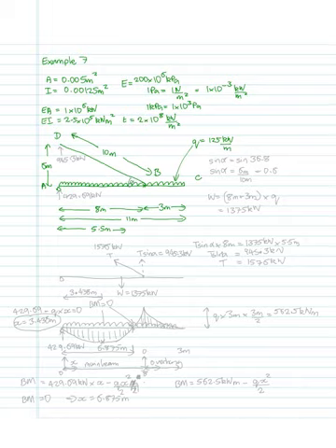If we wanted to know the angle alpha, we could say alpha is equal to 36.8 degrees, calculating alpha based on 6 over 10. Sine of alpha is 6 meters over 10 meters, which is equal to 0.6.